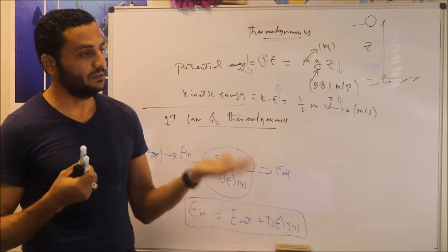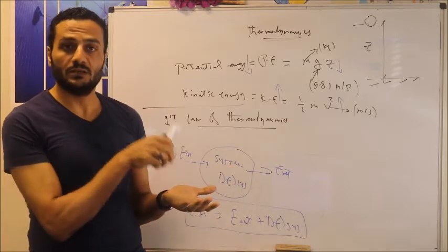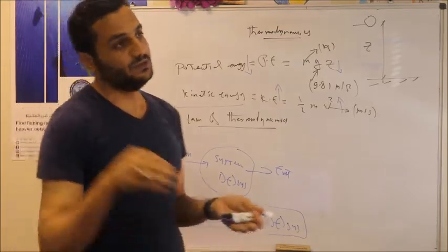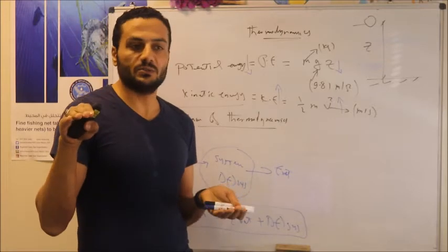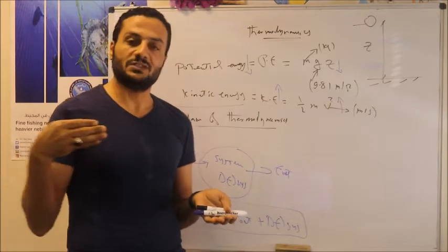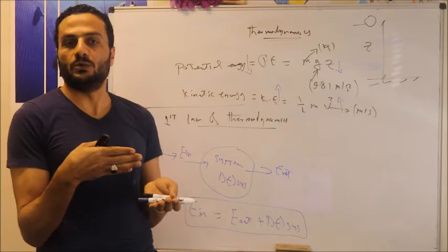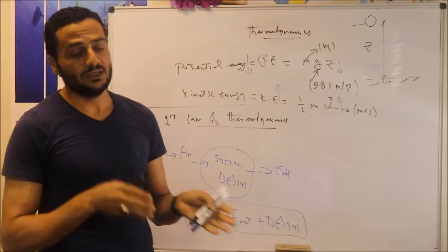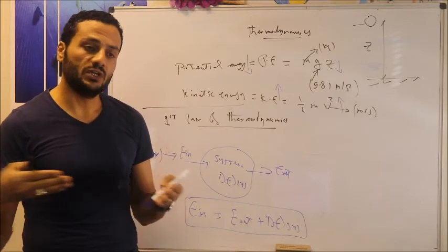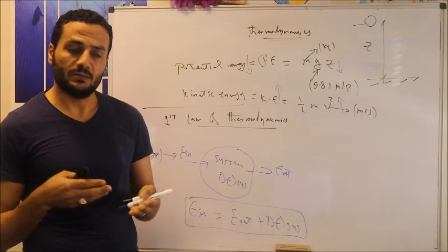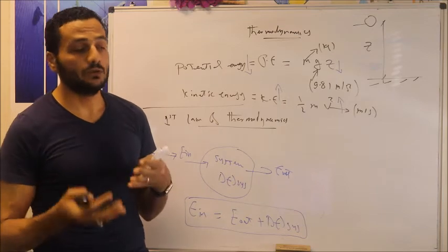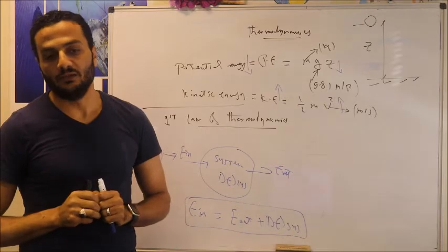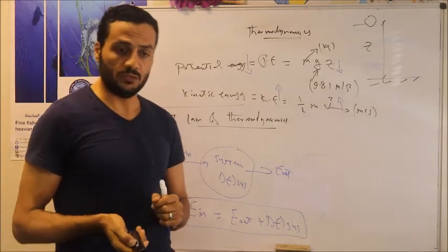So in this case I need to absorb heat, or have heat transfer, from the low temperature level to the high temperature level, and based on thermodynamics this is not possible by itself. So in this case we have to supply work to this system. In the case of a fridge, we have a compressor that is connected to an electric motor, so electrical power comes in to drive this compressor in order to absorb the heat from the low level to the high level. Okay, this is also an application of thermodynamics.